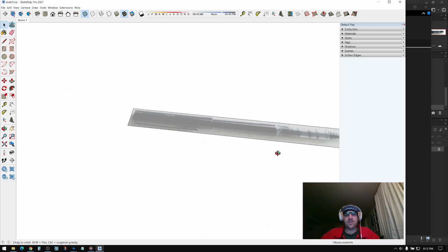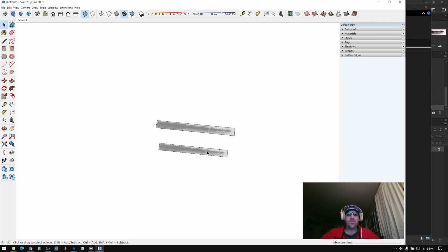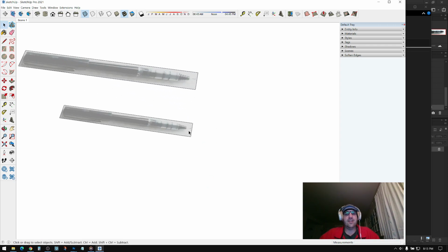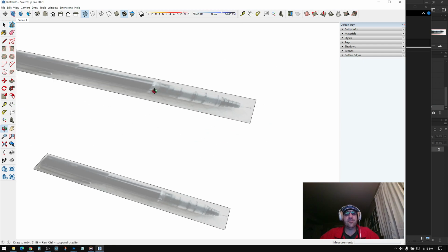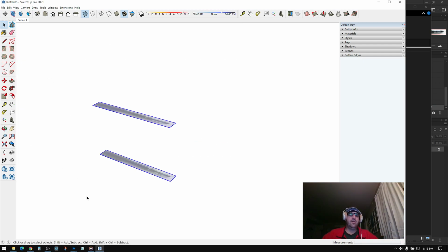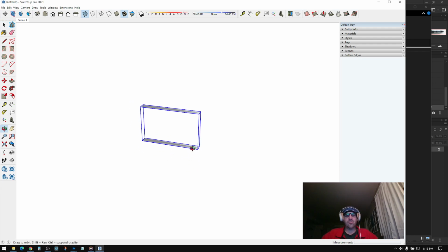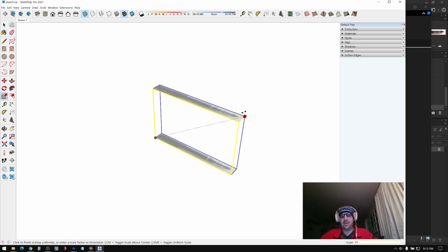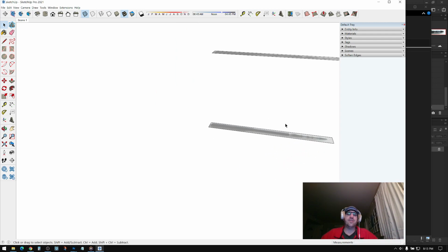And there's another trick. Since this object is so small, it's very difficult to model because the units are too small, and the snapping will want to snap to 1/16 of an inch usually, or 1/8 of an inch, and you can't model this much detail. So what I usually do is blow up the object, turn it into a group, and use the scale tool, type in 10, enter, and that will scale it up by a factor of 10.